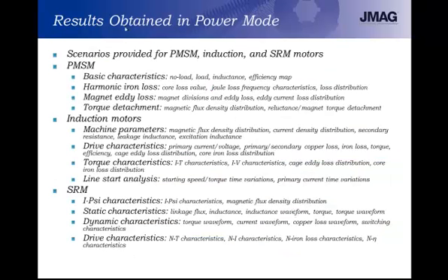The benefit of Power Mode is that we don't just run a basic output of some of the motor performance parameters such as what we saw in Quick Mode. We actually do a full analysis scenario. These scenarios are provided for PMSM, or permanent magnet synchronous machines, induction machines, and switch reluctance machines. The scenarios that we have available for the permanent magnet synchronous machine are a no-load analysis, a load torque analysis, an inductance analysis, and an efficiency map analysis.